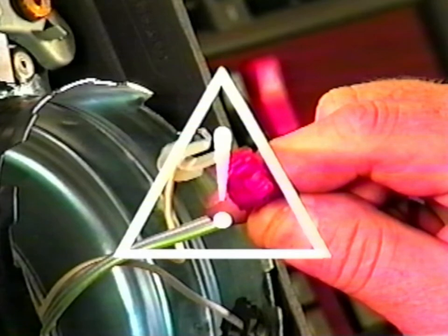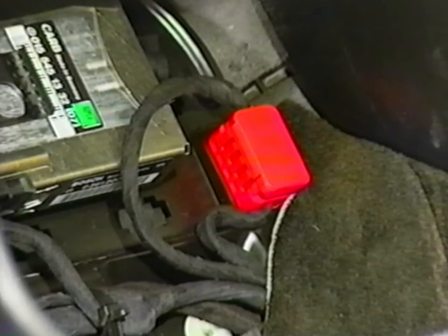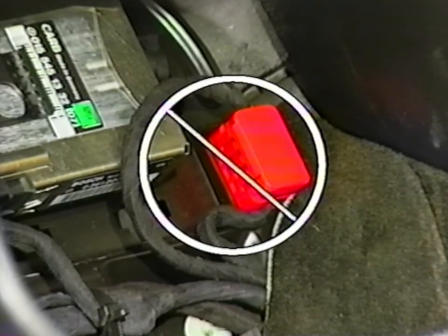If welding on the vehicle, the battery and SRS control module must still be disconnected, as previously required. Since the SRS is now tested using the handheld tester, the test connection as used on other models has been eliminated.